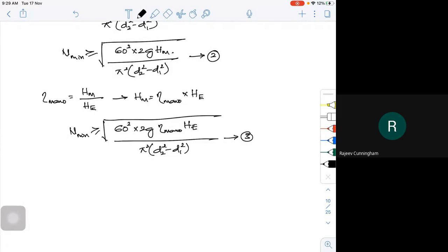The moment the pump reaches 120 RPM or slightly greater, maybe 300 RPM or 400 RPM, which is greater than 120 RPM, the pump will start delivering the fluid. As this number keeps increasing towards its rated RPM, the pump will deliver more and more fluid, that is, the quantity of discharge will increase. But the pump has to run at this minimum speed. And this is how you can get the expression, based on your manometric head or based on your Euler head.